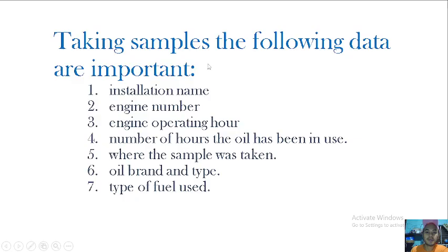So taking samples, the following data are important. If you want to take samples of your lube oil and send it ashore for testing, these are the important information that must also be taken: installation name, engine number, engine operating hours, the number of hours the oil has been used, where the sample was taken, the oil brand and type, and the type of fuel used.